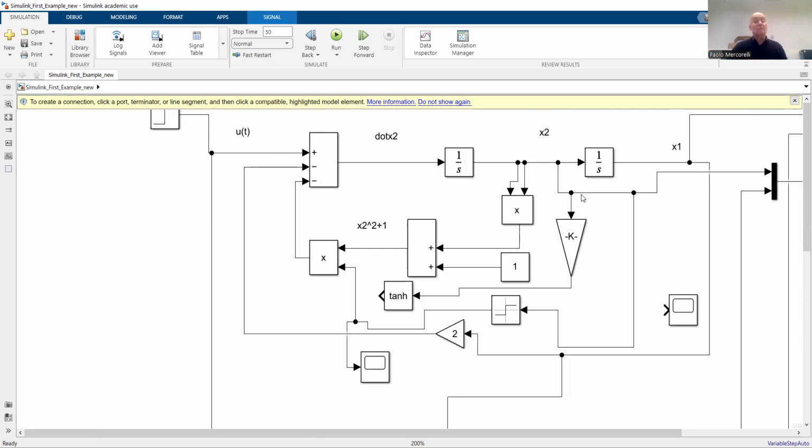But if I measure x2, it seems that I don't have information about x1, but I have it, thanks to the spring. Therefore, in some actuators, we introduce the spring if we have some system or something which realizes the feedback in order to obtain the observability. Without the spring, if I measure x2, I cannot have information about x1, because we don't have feedback in the system. Do you remember the concept of observability? Feedback to get information everywhere.